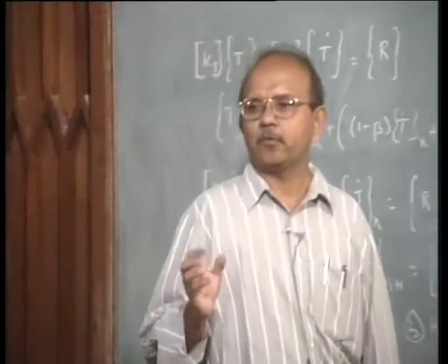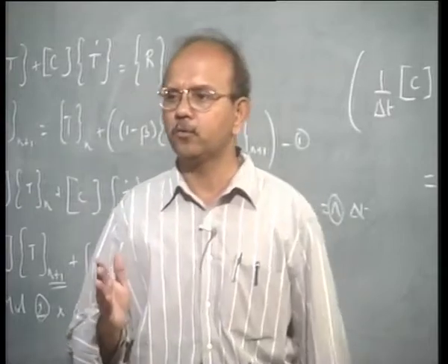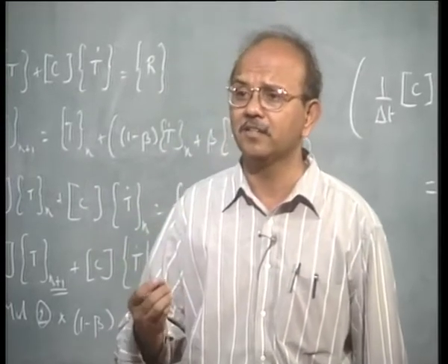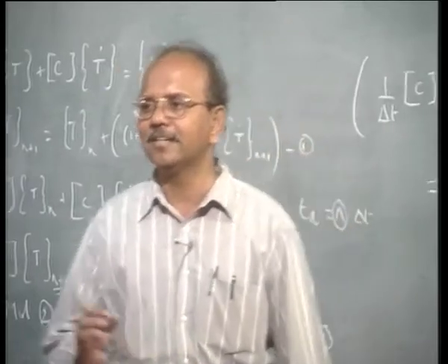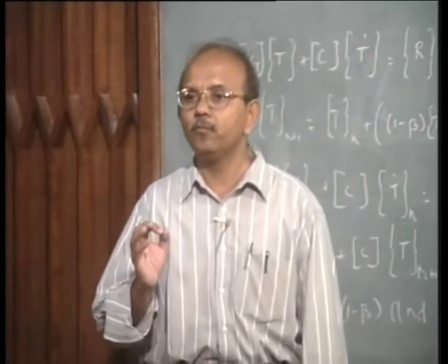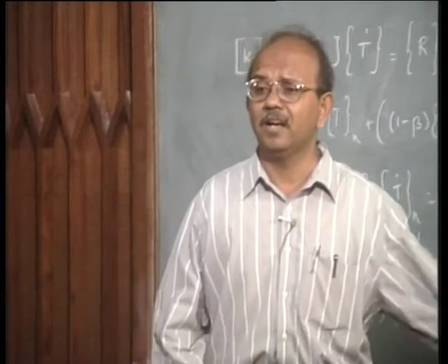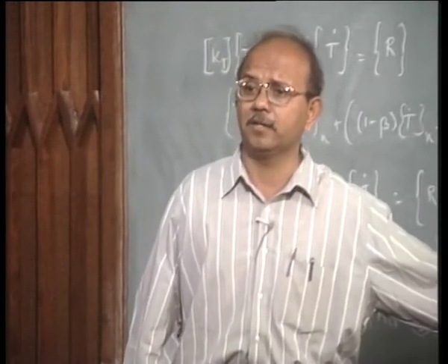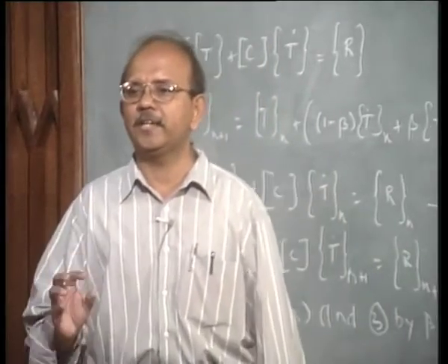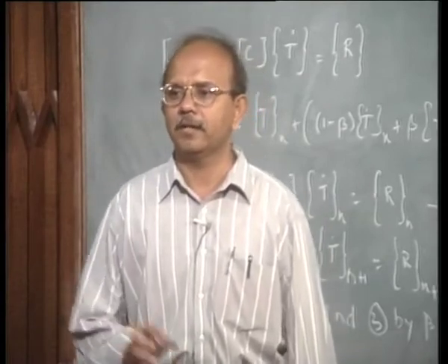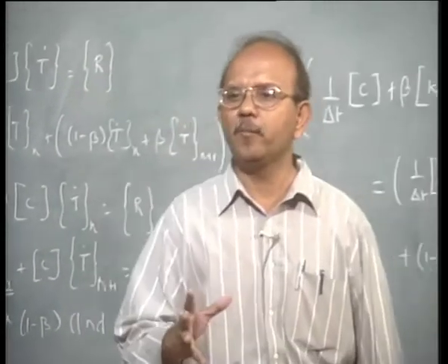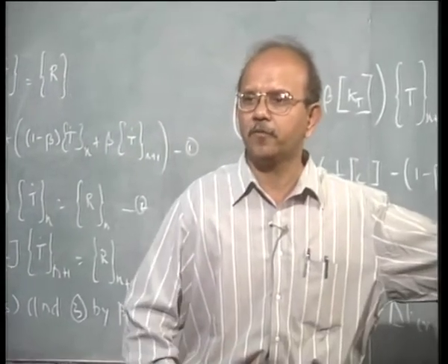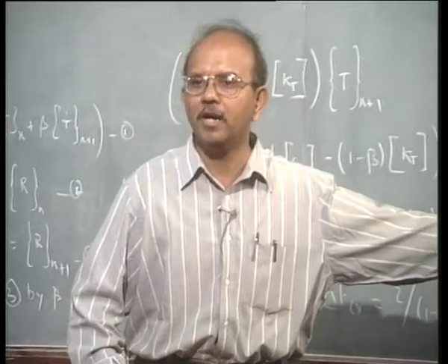Now the question actually has a different meaning which people don't understand. Even people who ask this question don't really understand why they are asking it. It's not a question of suspecting finite element analysis. The meaning is that you have made some assumptions. The assumptions are, say, thermal properties. Maybe you have made some assumption on the heat input, say for example a Gaussian distribution heat input.